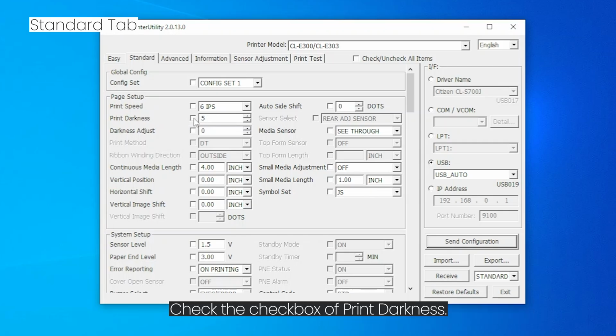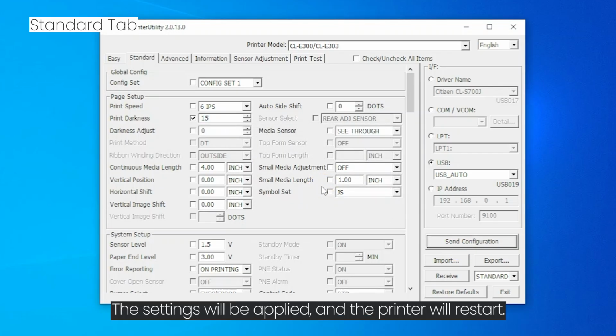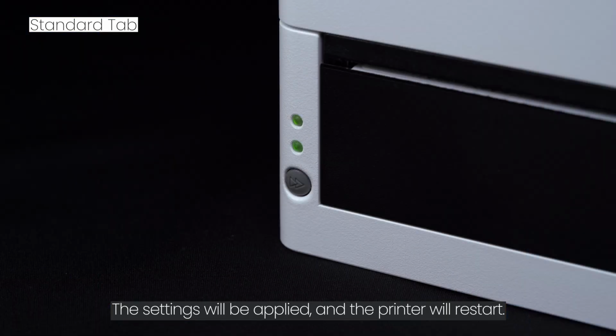Check the checkbox of print darkness. Change the value to 15. Click Send Configuration, and then click Yes. The settings will be applied, and the printer will restart.